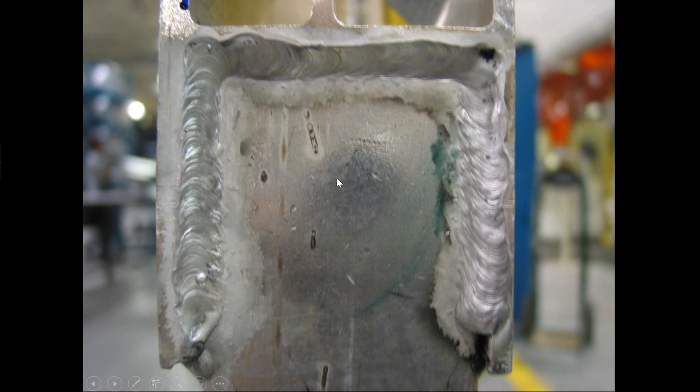This is for you to speak to quality. I don't want you welding anything unless you have to weld it. You're not doing the strength any favors. So if you see a situation where, oh my God, this could be called out as 3 separate welds, if it's called out as 3 separate welds, it's okay to have this, because the length of the weld will probably be from about there to there.